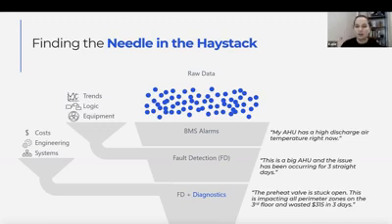So it lays on top of your BMS system. It pulls in information and data from your BMS and maybe some other potential data sources such as your metering systems or your lighting systems. It pulls it all into one. And then it will also pull in historical information, the logic that's written within your building automation system, so any of those sequences of operations.